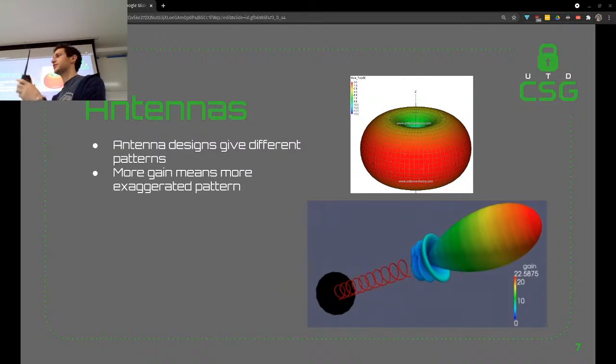But basically this gives off that signal path like you see on the top there, which is just a radial signal, and then there's 2 null points, which is just the top and the bottom of the antenna. So if I want to transmit from one dipole antenna to another dipole antenna, it's best to have them parallel with each other. And sometimes you'll see, like if you've ever set up, or you've seen like a TV receiver